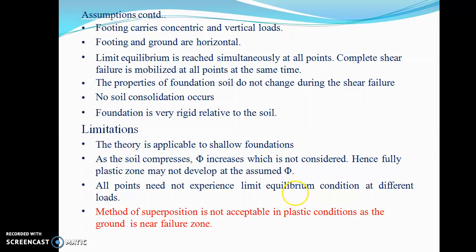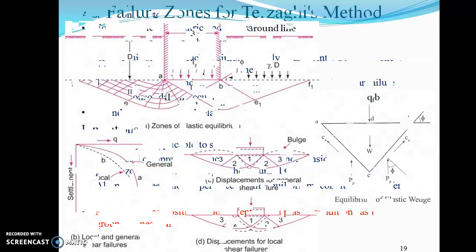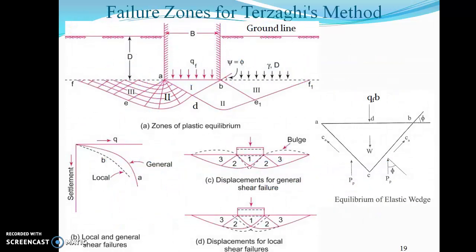All points need not experience the limit equilibrium condition at different loads. Method of superposition is also not acceptable in plastic conditions as the ground is near failure zone. This is what I spoke about, okay, sometime back. And the next slide. Okay, now let's have a look at this slide. Now this is what is happening for shallow foundations.